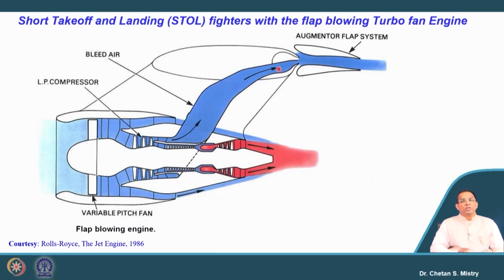So, here we are stopping with this particular lecture, and I am sure you have now understood what we mean by the types of turbofan engine. Specifically, we have started discussing the two spool configuration, that is the unmixed two spool configuration, in which my fan and compressor are on the same shaft, rotated by the LP turbine, and the HP compressor and HP turbine are on the other shaft. In the next lecture we will try to solve numericals, and then we will start discussing the next configuration of the engine. Thank you very much.